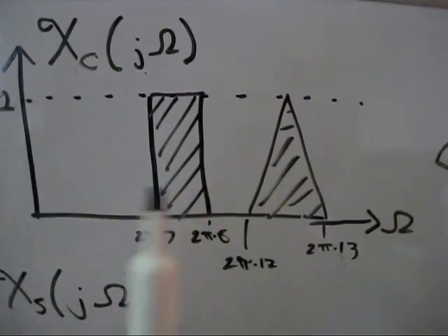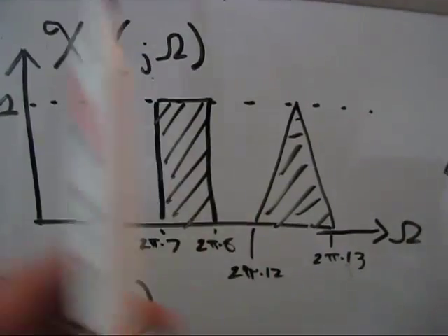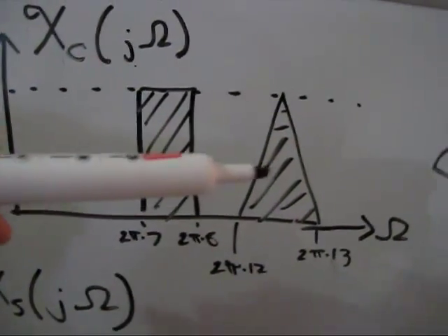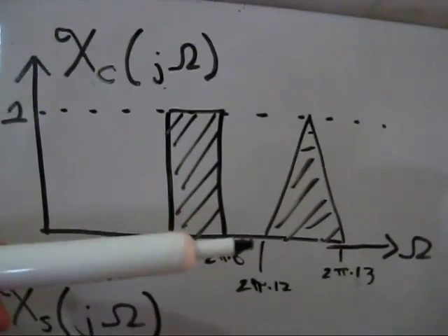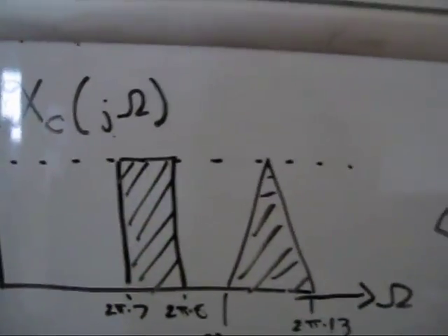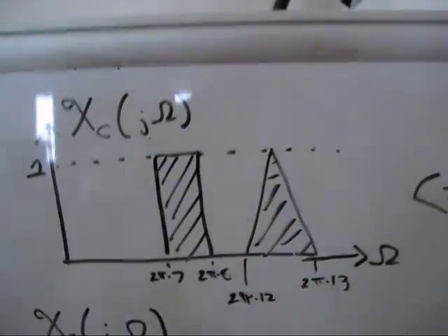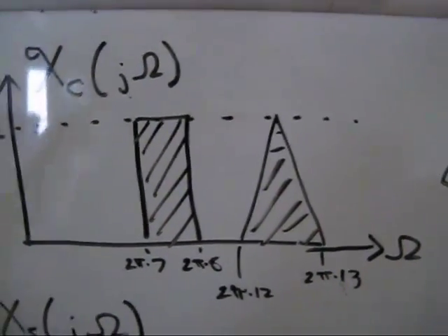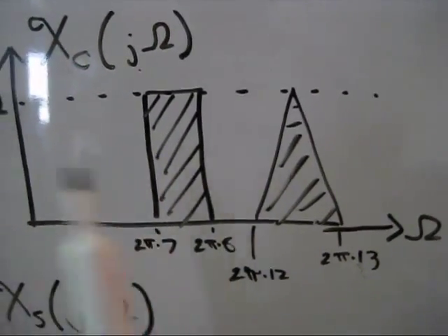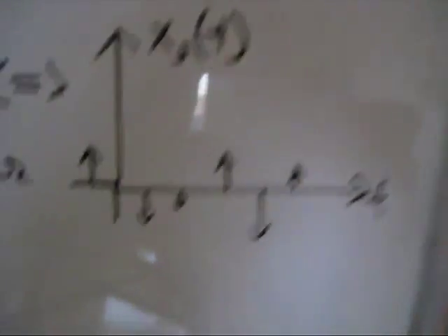Now what we're going to see is that that's actually not necessary to be able to sample all the information in the signal and accurately reproduce it, if you were to then output it back into the real world after sampling it, without any loss. The first step in mathematically establishing a sampled signal is to multiply your signal by a Dirac comb.